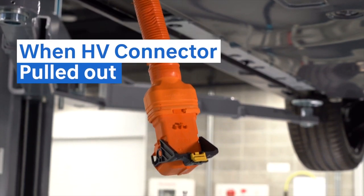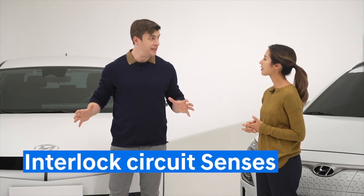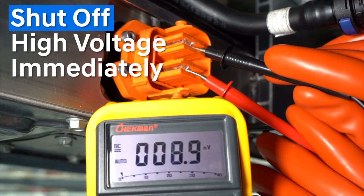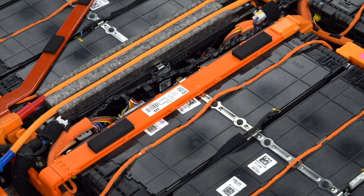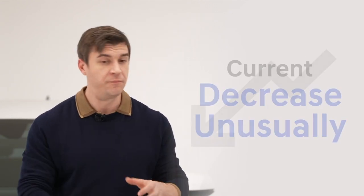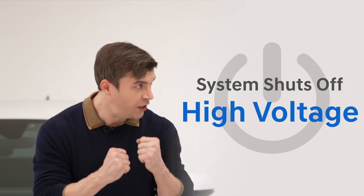In fact, so important, I'm going to explain in greater detail. When the high voltage connector gets pulled out, the interlock circuit senses that, and it shuts off the high voltage immediately. When the cable gets opened or it's short-circuited, the current that's flowing through the high voltage system as a result will decrease unusually. The system will detect that and shut off the high voltage.